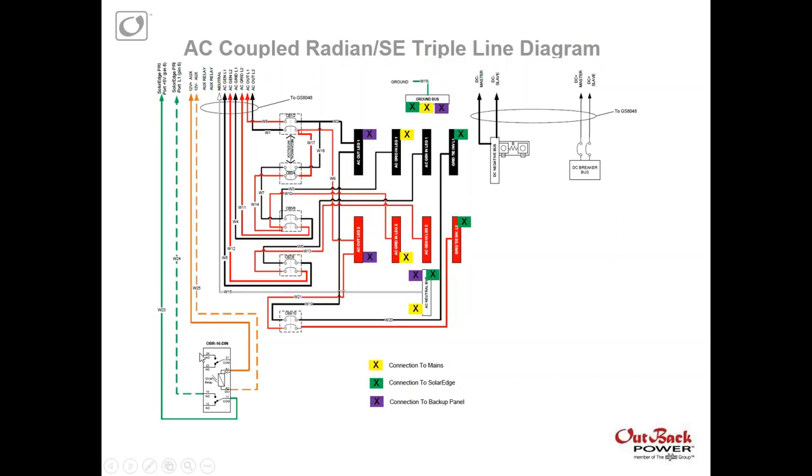We're essentially using a relay. This is similar to what we would have used for a diversion control relay in the past, but this relay is operating on a voltage signal, and when the voltage on the batteries climbs to a certain point, say 59, 60 volts, we're going to introduce a delay there just to make sure it's not a momentary thing. And if that gets to 1 minute of too high of a voltage, this relay is going to be told by our AC coupling mode in the Mate3 that it needs to open that relay and stop accepting power from